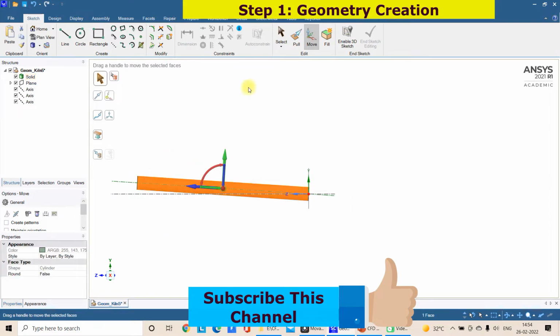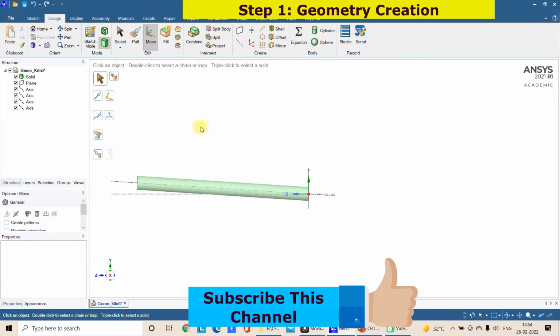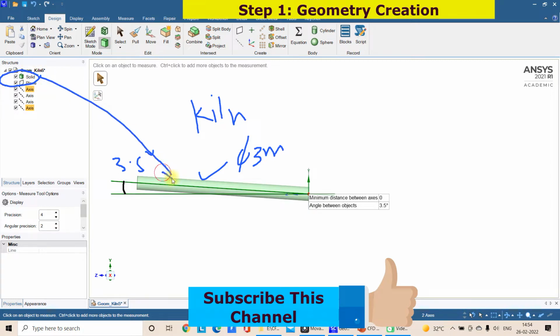And then click here, select for the center axis and check this angle and this angle, how much is there. This angle is 3.5 degree. See, this angle between this is 3.5 degrees. This is a cement kiln which has a diameter of 3 meter. That means this is a kiln, and this is the name of the zone created for this volume.